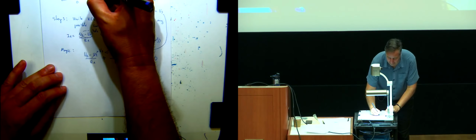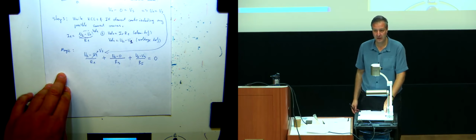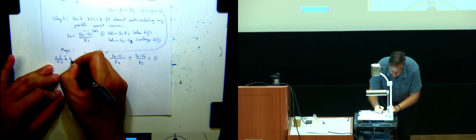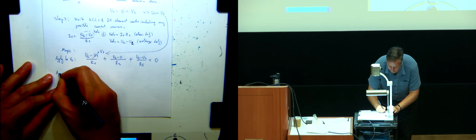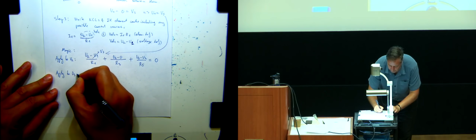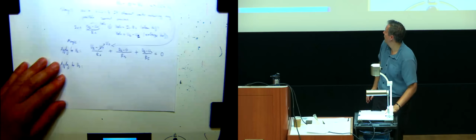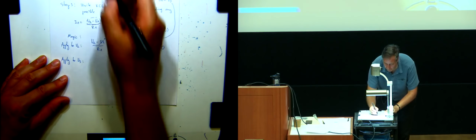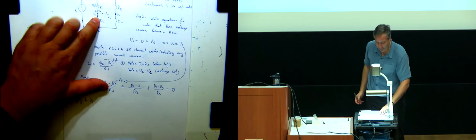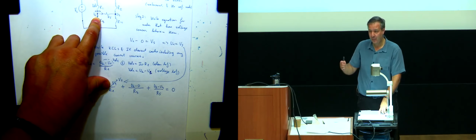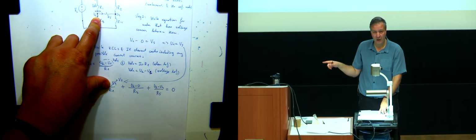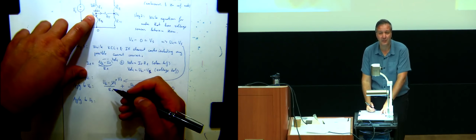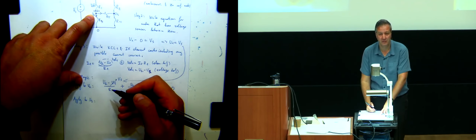Yeah, so let's apply this magic on the other node, U3. So applying to U2, and now apply to U3. Okay? So let's see how this one goes. Let's do it. Now, notice what I was doing here. Just to make my life easier, I picked the currents always going out of the node so that I always start with U2. So I'm obeying the passive sign convention, right? So everything's working out.